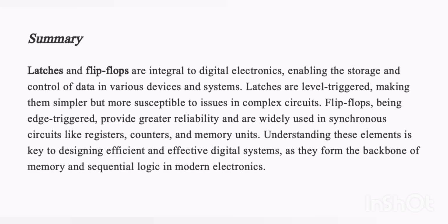Latches and flip-flops are integral to digital electronics, enabling the storage and control of data in various devices and systems. Latches are level triggered, making them simpler but more susceptible to issues in complex circuits. Flip-flops, being edge-triggered, provide greater reliability and are widely used in synchronous circuits like registers, counters, and memory units. Understanding these elements is key to designing efficient and effective digital systems, as they form the backbone of memory and sequential logic in modern electronics.